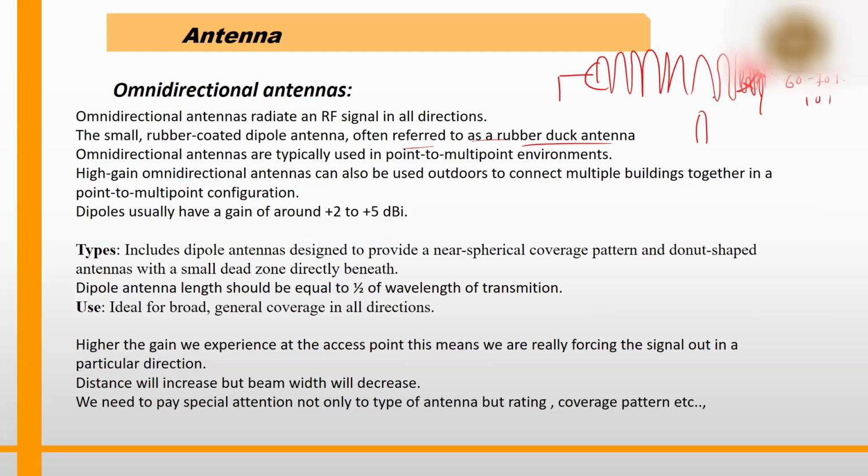But as a wireless engineer, you should know all these concepts and nuances of these topics, because you will purchase an antenna and you will mount it, and you purchase like 4 antennas you mount it, but your clients are not upgraded. Your clients are operating at less power values, whereas your antennas are sending the signal far away, but the clients are not able to respond back. The antennas or the AP is able to reach the client, but the client is not able to reach the AP. So those kind of situations should not happen. So you need to properly do a survey, proactive survey.